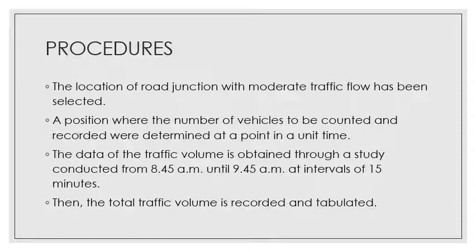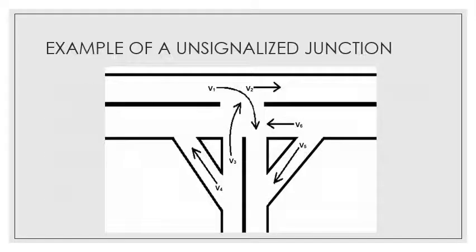Then you record the number of vehicles according to classes: car, motorcycle, bus, van, small lorry, large lorry, etc. You put them in a proper table, and at the end we will calculate the total number of vehicles.